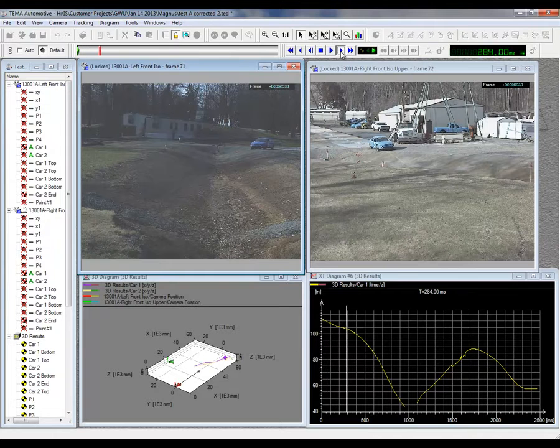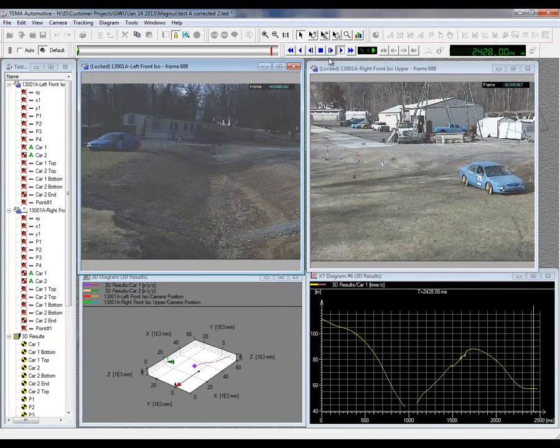Here we measure the motion of a vehicle in an off-road excursion in 3 dimensions using 2 cameras. Using relative orientation we do not need a survey, just a straight line distance between 2 points in the field of view. This test by George Washington University staff achieved an accuracy of about 1 inch using this method.